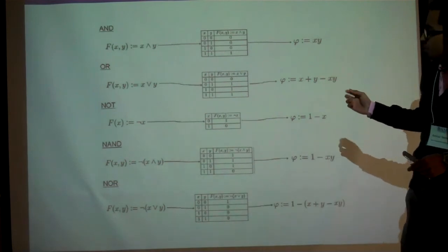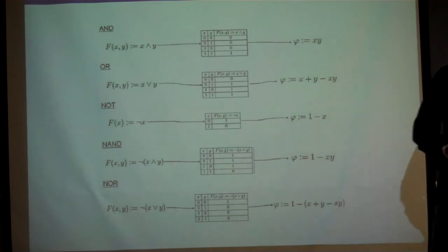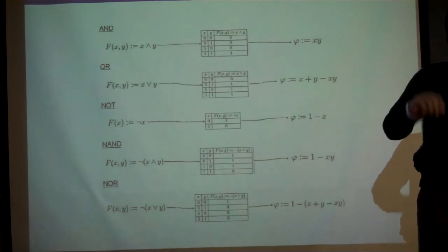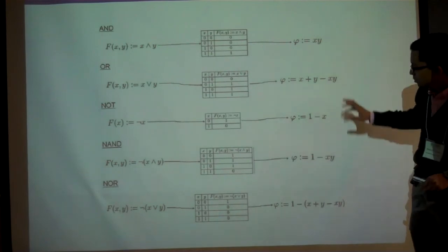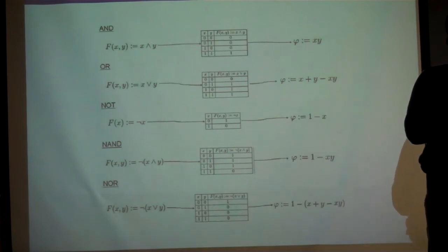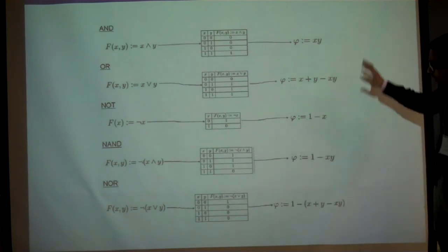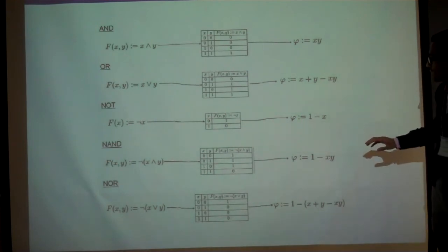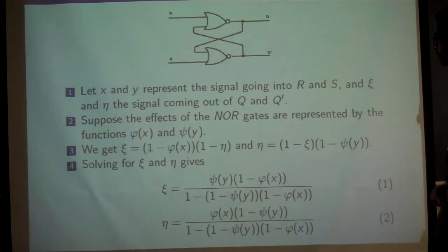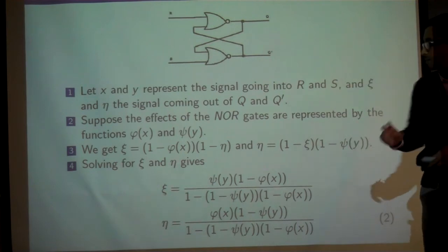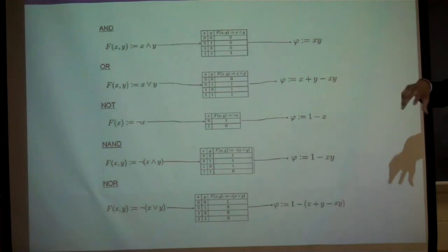So we weren't really satisfied with this because it was done in an ad hoc manner. What we wanted to do was go from the ground up. So we wanted to go to the level of the gates and try to get models for the gates, and then build models of any sort of circuit using these models for the gates. So we came up with some simple models for the gates, and we used these to model the RS flip-flop.